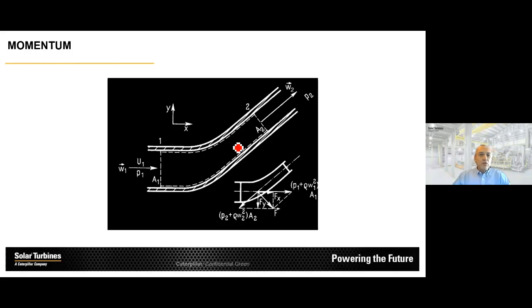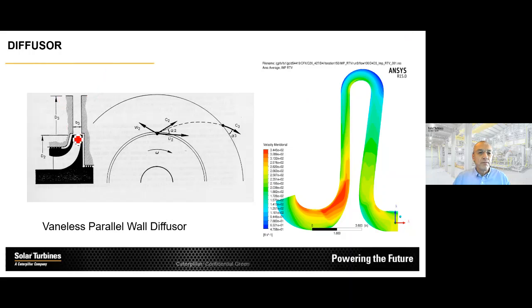And I do that in a rotating system. So that's happening in the impeller, and then in my diffuser, I convert, and you see that here very nicely in the colors of that graph. You see higher velocities at the inlet, lower velocities and higher pressures at the outlet. So essentially I trade in the diffuser velocity for more pressure.